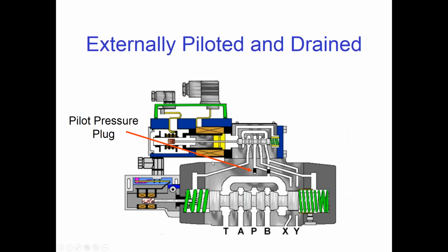Inside, so here's our direct operating valve, just like we looked at before, and you see the LVDT here, the coil here, and the valve spool here. And this is the main spool right here, so that we can move a much larger amount of flow and operate a larger actuator or move something very fast. And we also have an LVDT on the main spool to feed back the main spool position.